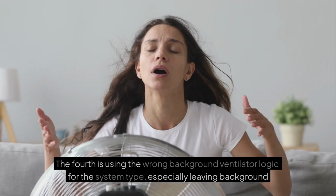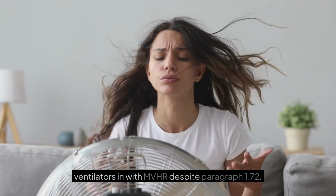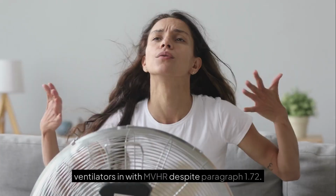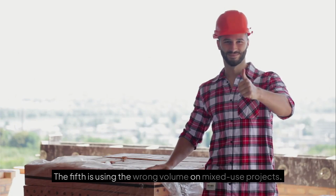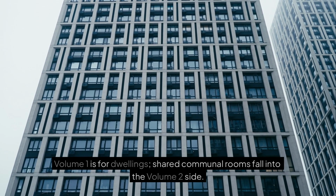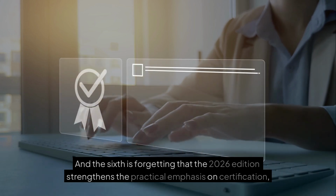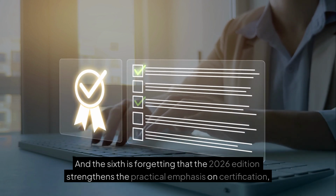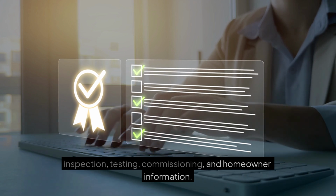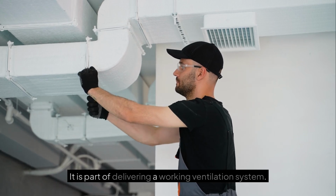The fourth is using the wrong background ventilator logic for the system type, especially leaving background ventilators in with MVHR despite paragraph 1.72. The fifth is using the wrong volume on mixed-use projects. Volume 1 is for dwellings. Shared communal rooms fall into the Volume 2 side. And the sixth is forgetting that the 2026 edition strengthens the practical emphasis on certification, inspection, testing, commissioning, and homeowner information. That is not just admin. It is part of delivering a working ventilation system.